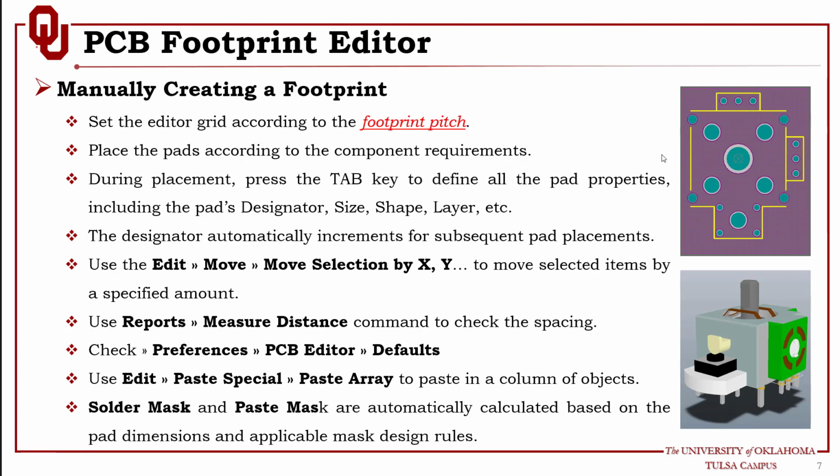And I picked for the manual creation, first we need to create a through-hole footprint like this one. This is basically a 2-axis joystick with a center switch. As you can see here, all these pins are through holes. We have mechanical holes, and also we have electrical holes, if you will.